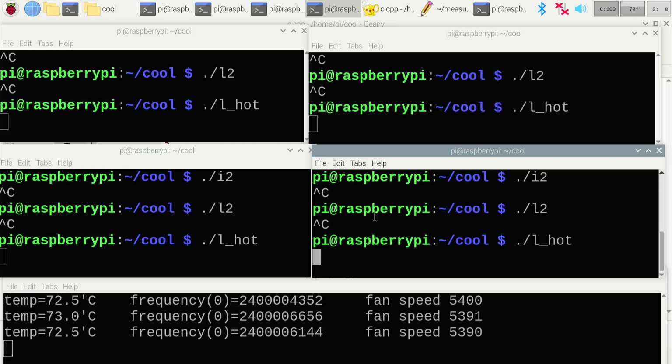Let's take a look at the program execution of my stress test. We will see that the temperature rises over 75 degrees Celsius. The fan spins at 8000 rounds per minute. This is sadly loud. The fan maintains its speed until the temperature has dropped clearly. The fan then only rotates at around 5000 rounds per minute. It only accelerates again when the temperature is above 75 degrees Celsius again.